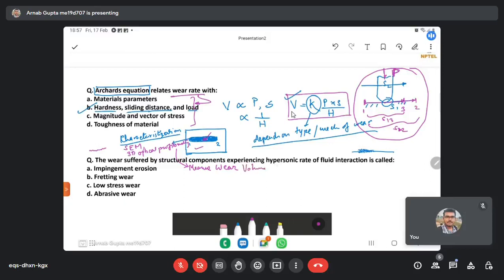Okay, so it will obviously be more accurate than what you have estimated using this equation, because in the real scenario you will see that there are chances of more wear near the ends or at the center. So under different loading conditions, this thing can happen, because you have this indenter, or what we call as the slider.